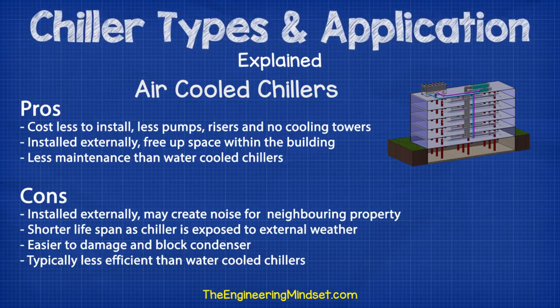Let's now have a look at air-cooled chillers. So some of the pros for using air-cooled chillers is that they cost less to install, and that's because they use less equipment. Air-cooled chillers require less space. They can sit up on the roof or out in a car park, and they do not need a mechanical room. This means more space within the building for business purposes.